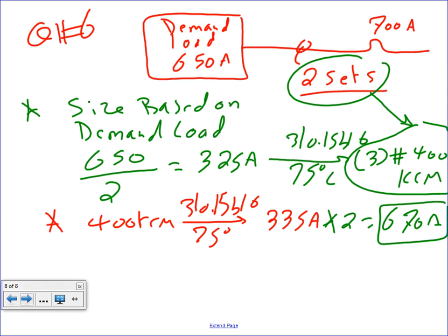After 800, you start matching the cable to the overcurrent protection device. I will do this more when we come to the commercial, guys. We do a lot of examples about that one. But right now for this exercise, you always size based on the demand load.